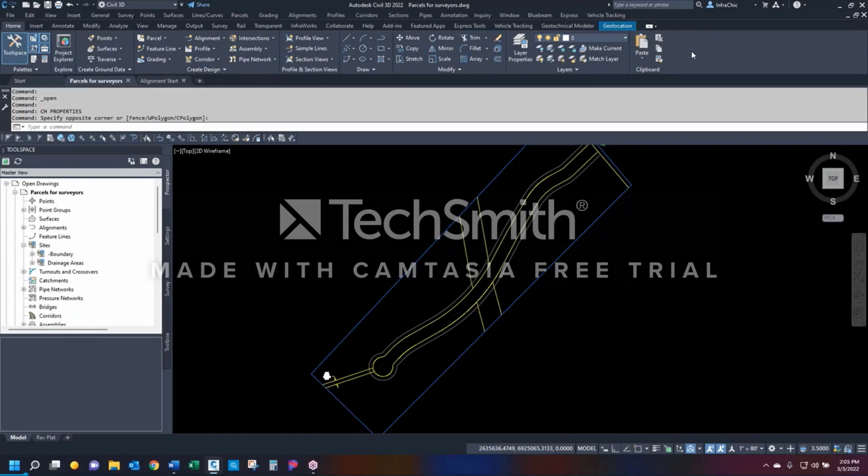Parcels. Parcels are stored in sites. Sites are found on your tool space. If your tool space is not open, it's on the third window, not in my first window. There it is. Tool space is found on the home tab of the ribbon. Tool space button on, tool space button off.